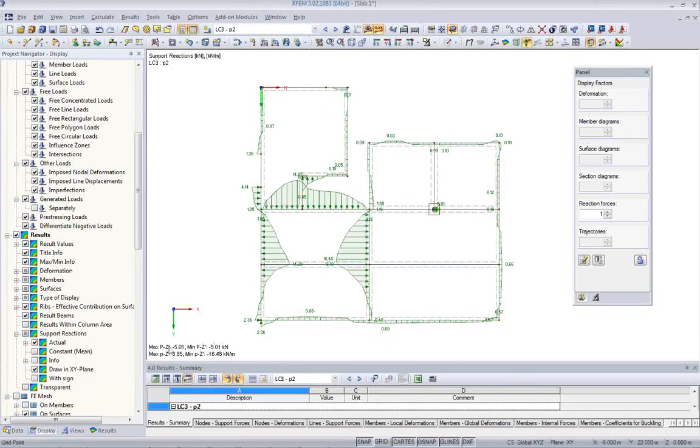Often engineers do not work with the real lines of the support forces because when there is a masonry wall, the force transfer is not one-to-one from the support of the slab down to the next maybe wall below.